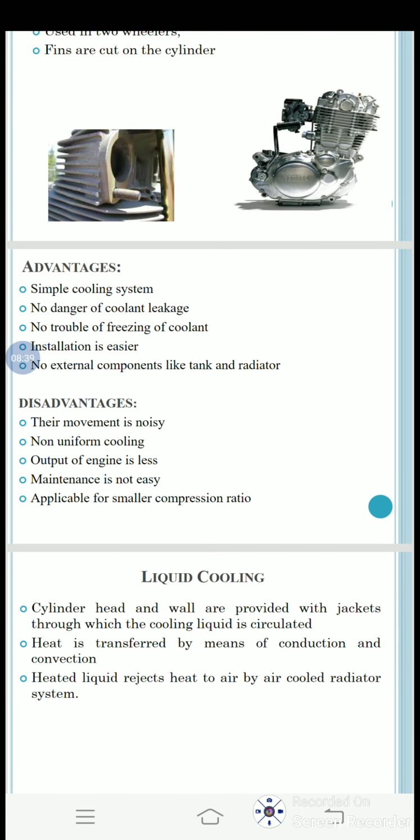Let us see the advantages and disadvantages. It has a simple cooling system, no danger of coolant leakage, no trouble of freezing of coolant. Installation is easier. No external components like pump and radiator. Then we'll see some disadvantages. Their operation is noisy, non-uniform cooling, output of engine is less, maintenance is not easy, applicable for small compression ratio.